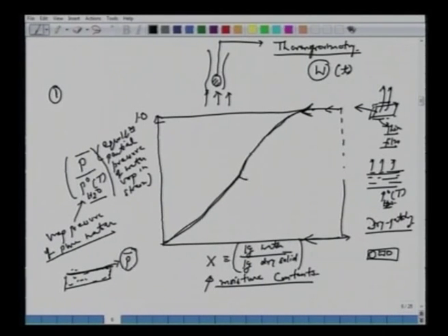So let's say this is wood. Wood has a very typical feature that for a long time it soaks a lot of moisture. So for a long time you will see that the moisture content decreases starting from certain values. So say from 0.35 to 0.3, this partial pressure at the surface can be assumed to be the same as the vapor pressure of pure water because it's a thin film here.